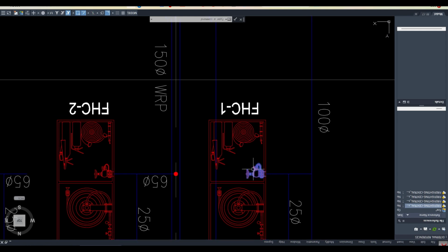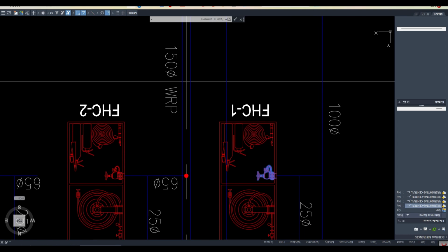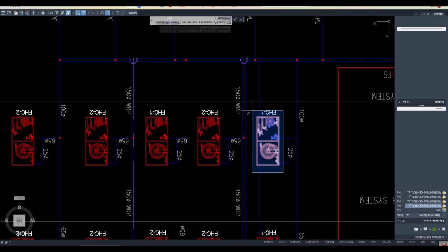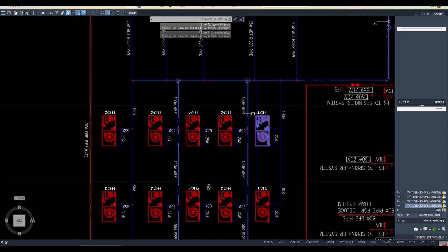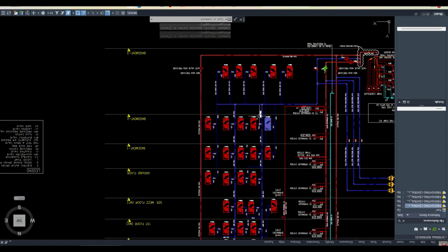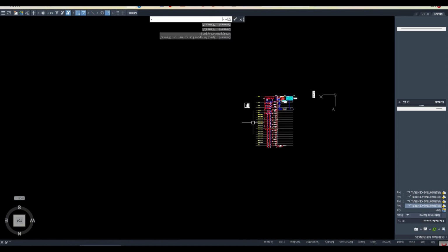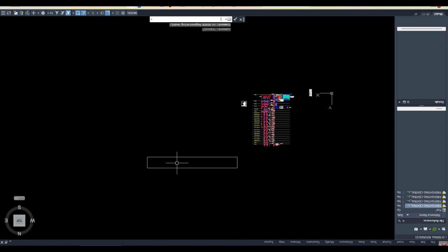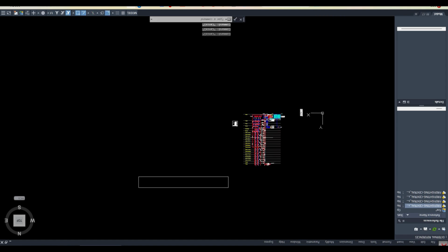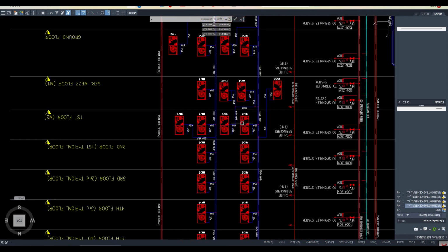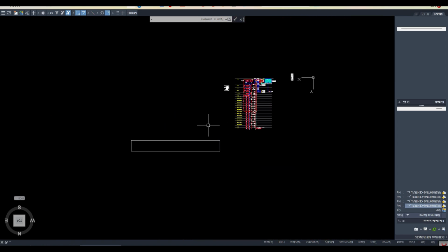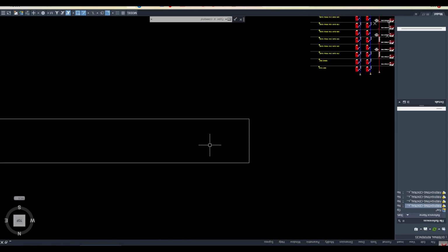Okay, and the length of this hose also is 30 meter. Okay, so it means this hose, this cabinet, we cannot keep more than 30 meter anywhere in the building. So for example, now I'll ask the question. Let's say I have a corridor like this. Okay, and another first rule is this landing valve or this hose reel, okay, it cannot be more than 6 meter away from the staircase.